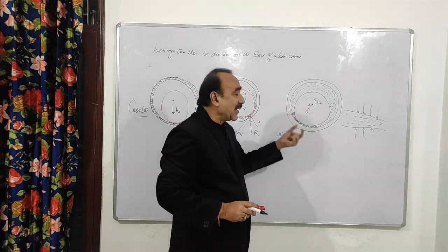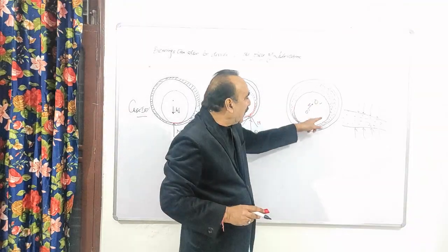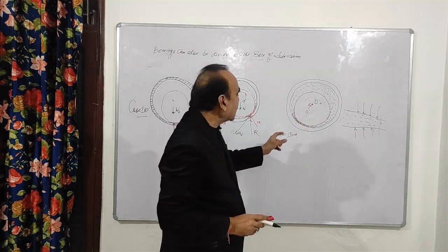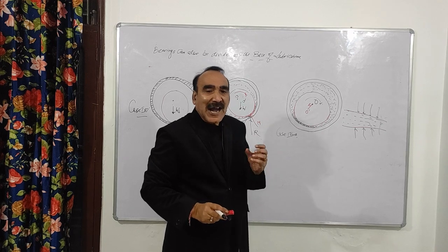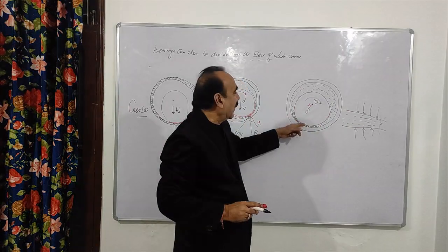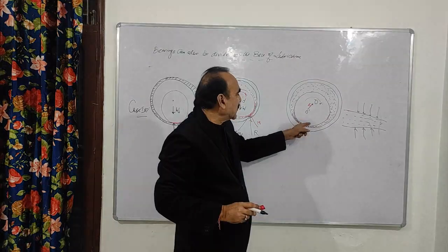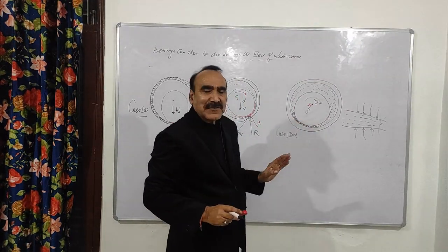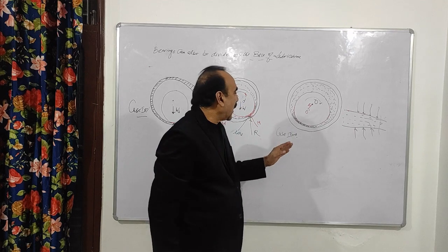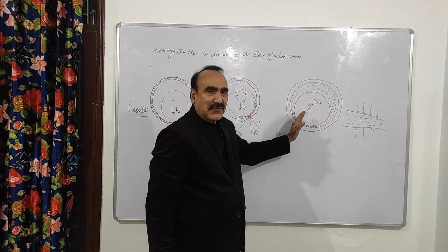So the pressure of the lubricant at this point will be so high at this speed that the bearing surface as well as the shaft surface are not in contact with each other, they are completely separated due to the high pressure which is created due to the wedge, because it is narrowing down here, there is a converging section here. So when there is convergence, the wedge will be created, and in that wedge the high pressure will be developed. So this high pressure will separate the shaft and the bearing surface, right?